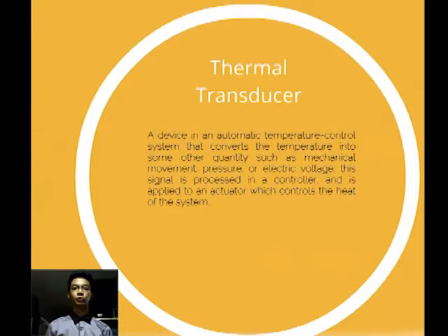A thermal transducer is a device in an automatic temperature control system that converts the temperature into some other quantity, such as mechanical movement, pressure, or electric voltage. This signal is processed in a controller and is supplied to an actuator which controls the heat of the system.